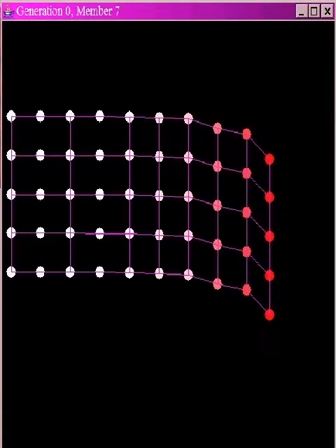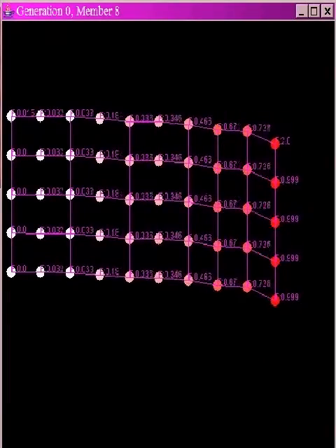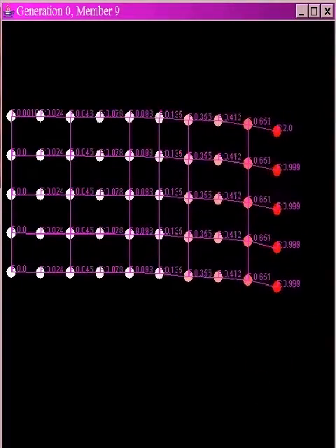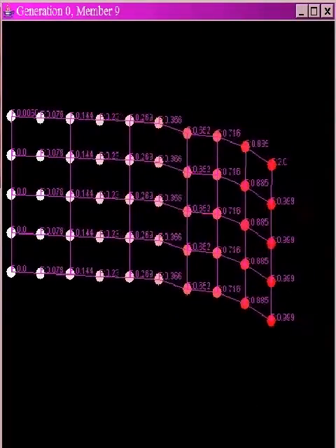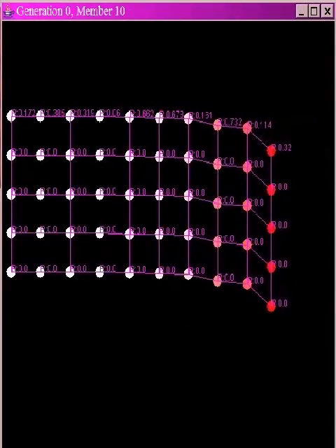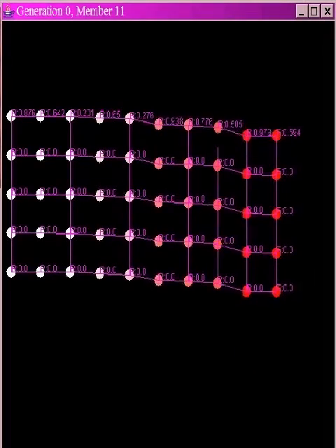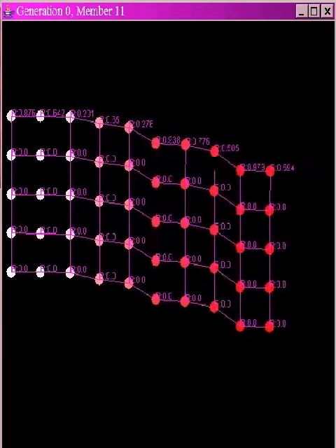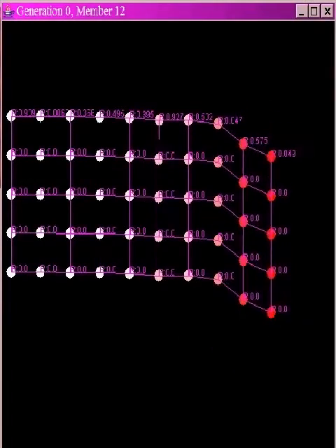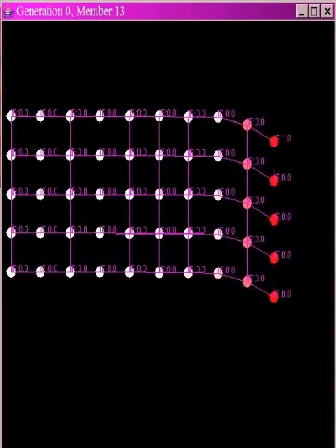After each individual is measured, the 5 most fit members are mated by selecting rod by rod a new rigidity for the offspring, randomly picked to be somewhere between the corresponding rigidity of each parent's rods. This results in 25 new individuals, which will include the 5 most fit individuals, resulting from each one mating with itself. 5 new random members are also generated, resulting in a new population of 30 individuals. A 2% mutation rate is applied to all matings. As can be seen, randomly generated materials do not generally exhibit the desired linear response.